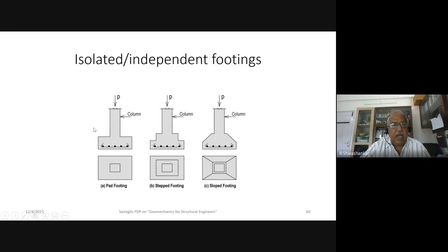That's geotechnical design. Coming to structural design, we design this footing as a slab, right? We have to check for shear. We usually check for one-way shear, two-way shear and punching shear. We check for bond, and we check for flexure. The IS code says, without going into detail, that the critical section for flexure, for bending moment, is at the face of the column. For that bending moment, you should have enough steel, right? And there are IS 456 recommendations on the minimum steel, bond length and all that.